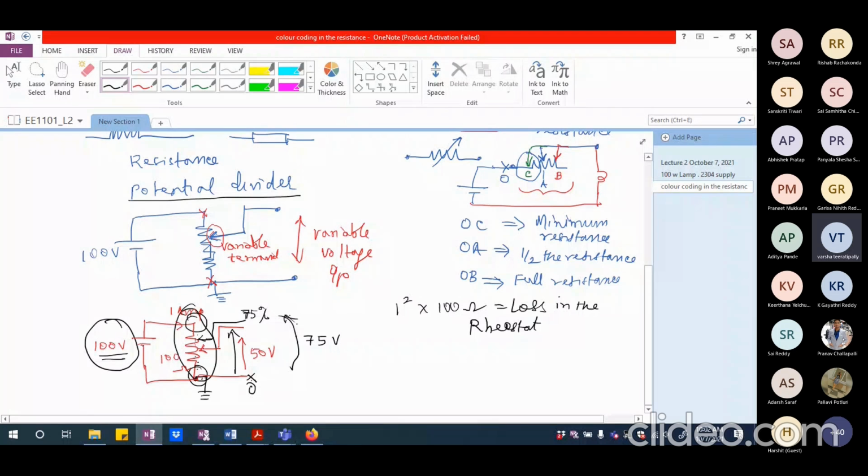Right? Here losses are spent through heat energy, right? Yes, or everywhere in any resistance. I mean, I was confused. Is it voltage drop or something? Just heat loss through the resistance. Please remember that voltage is not an energy unit. It is only a potential unit. When you multiply voltage by the current, it is the power unit. And when you multiply that with time, it is the energy unit.